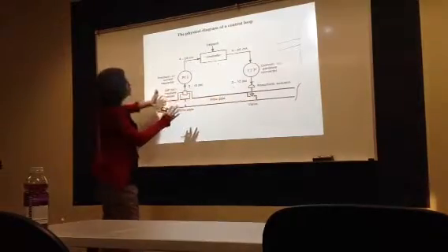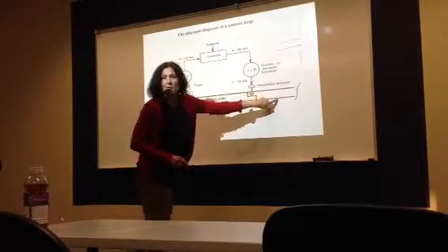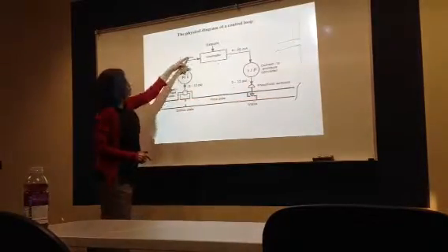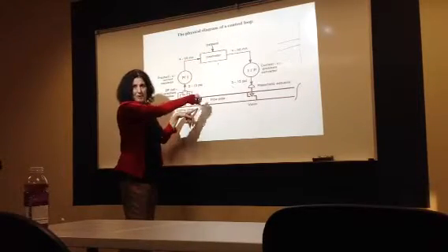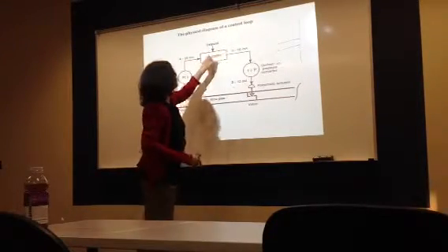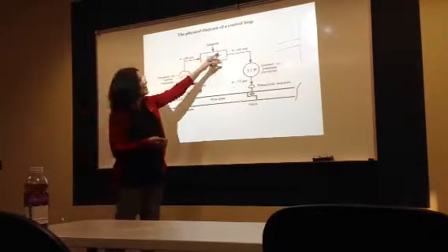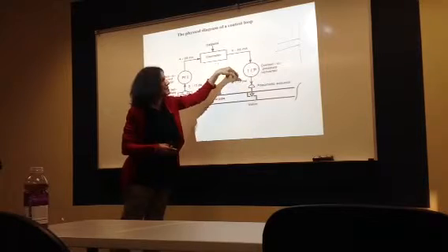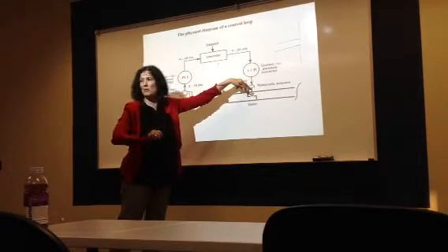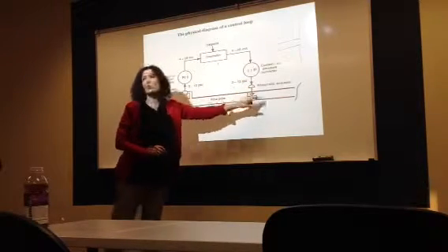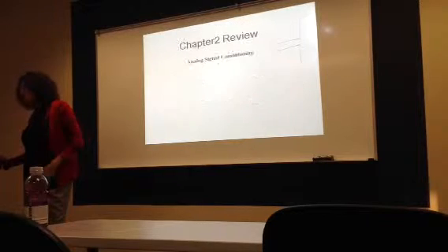All we're trying to do is control the flow inside this part, by measuring the flow and feeding it to the controller, and we have a target for the flow rate, right? And then the controller, whatever it is, PID, PI, decides on the output, and then the transducer switches from current to pressure, which activates the valve to control the flow. So all of that was in chapter 1.